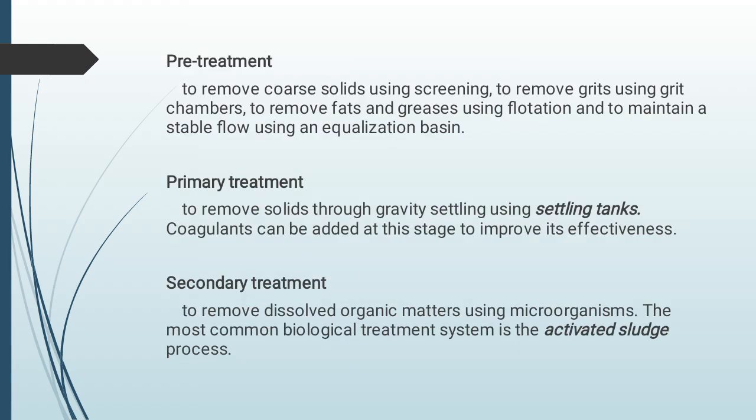Pre-treatment: to remove coarse solids using screening, to remove grits using grit chambers, to remove fats and greases using flotation, and to maintain a stable flow using an equalization basin. Primary treatment: to remove solids through gravity settling using septic tanks. Coagulants can be added at this stage to improve its effectiveness.